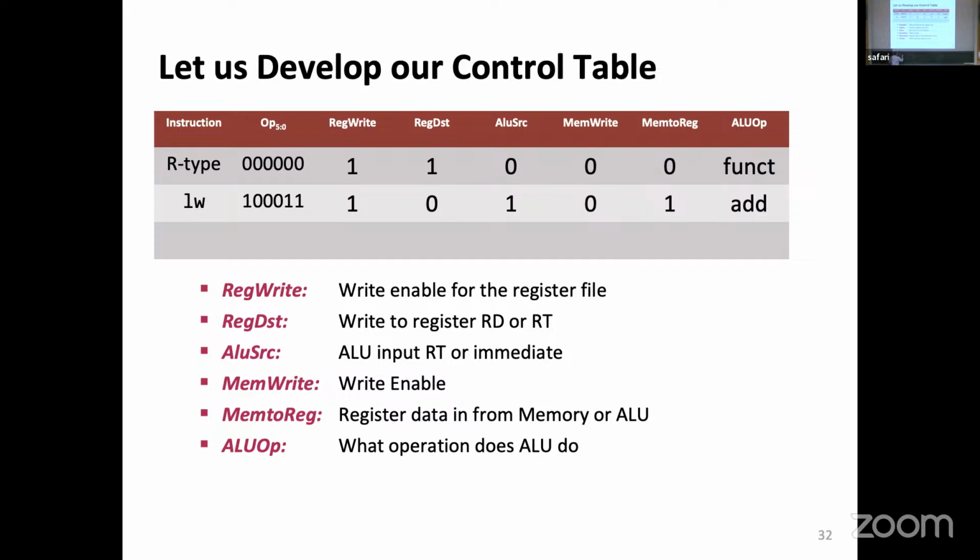So let me do it here. This is the R-type. Good question though. So let's quickly have this. The first 6 bits are the OP, and then you have 3 registers in the R-type. In the I-type, you have 2 registers. So this is immediate. This is register 1, this is register 2, this is register 3. I can never memorize which one is which, so I'm writing R1, R2, R3.